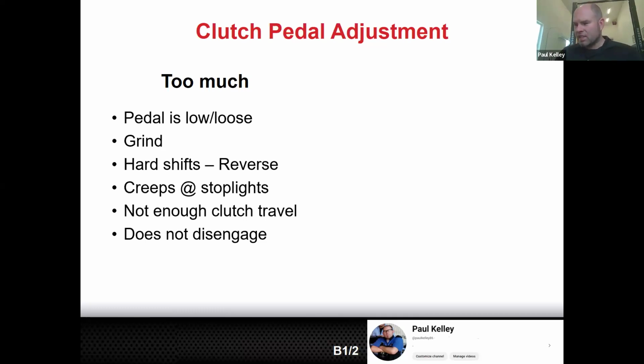And it's interesting because we spend a whole week on clutches and people like clutches, but the problem is the ASE will ask you a tricky question and you've got to know it front side, back side, inside out, from every different angle. So if it's after the work was performed, it's probably not because the slave cylinder was good but now the slave cylinder is bad. Makes sense? That'd be more like the adjustment maybe, or the incorrectly machined flywheel, or maybe a defective clutch part. Which is probably less likely on the ASE, but that was real life in this purple clutch situation.